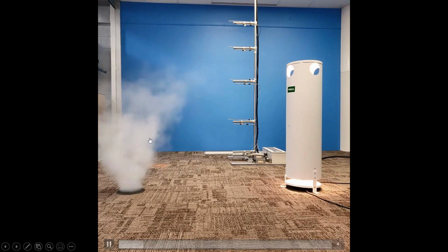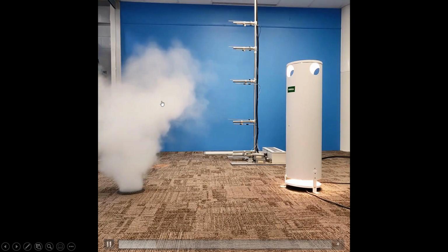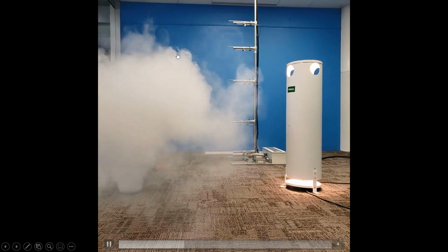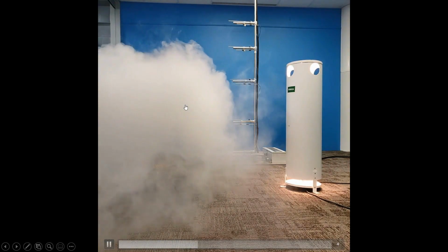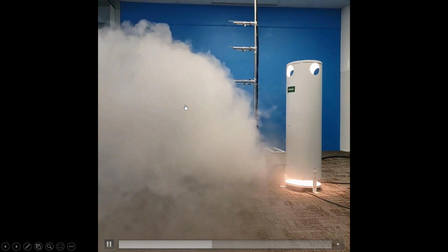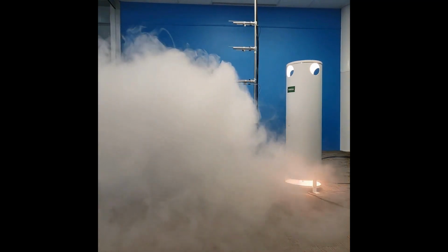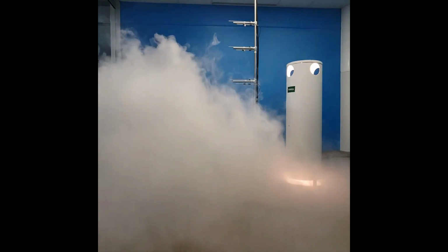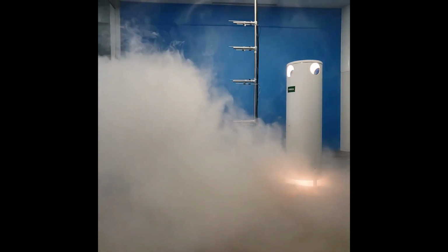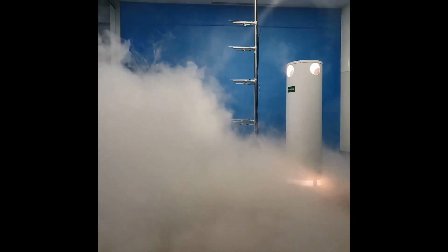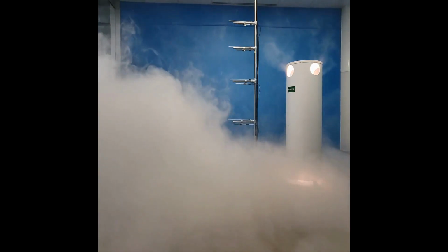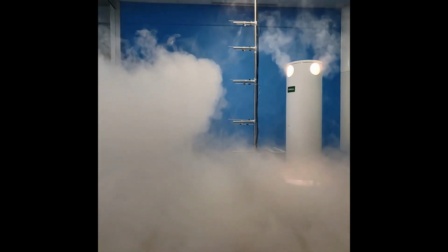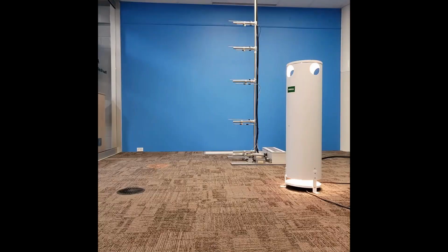So kind of on that note, here's the twist diffuser that we were talking about. Again, making sure it doesn't throw above 4.5 feet at peak design. And the idea is that this one is supplying more air than the displacement round floor diffuser, and it's inducing and pulling in some of that local room air in the occupied zone, but it's not breaking through the stratification and re-entraining contaminants that are already lifted up above the space through the thermal plumes and that upward displacement of airflow.